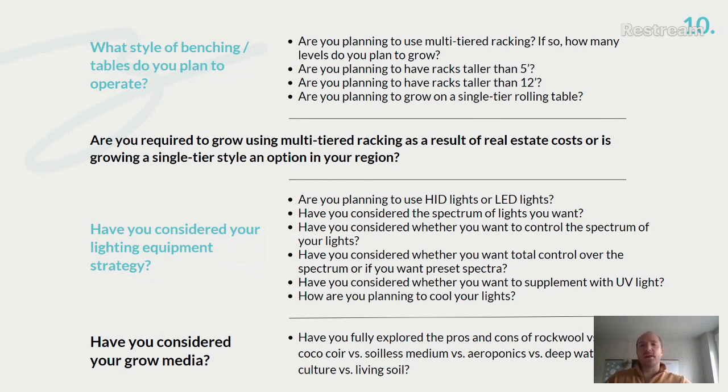Have you considered your lighting equipment strategy? This is going to really inform you on the manufacturer or the exact light that you're going to be using. And that will then determine how many lights you need, what your power requirements are, what your cooling requirements are for the HVAC in your room, and also the end product that you're going to create. For years and years, we saw everything was high pressure sodium or HPS lights. Now that LED technology has proven itself, I'm seeing 99% of facilities are being outfitted with LED lights.